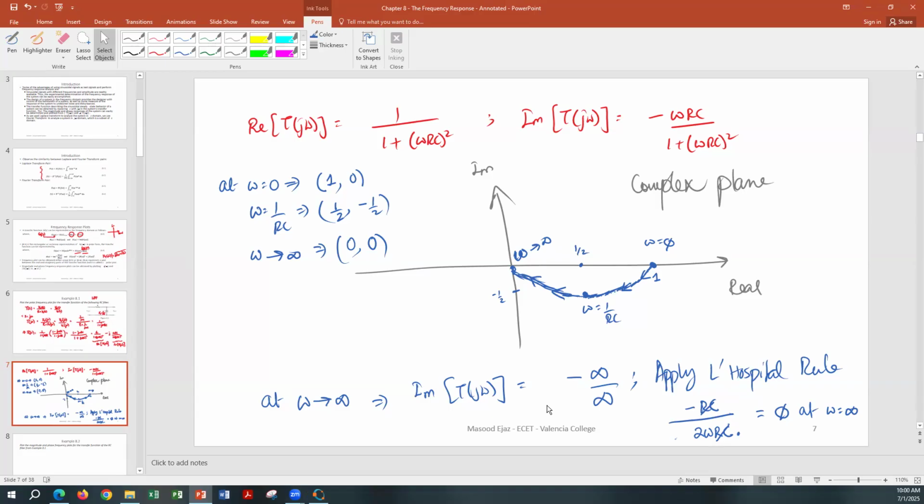Yes. I don't know if there's a built-in function, but it's very easy to plot in Octave. The same way we discussed to plot the root locus. Basically, when you plug in the value of omega in your transfer function, you're going to get a complex number.